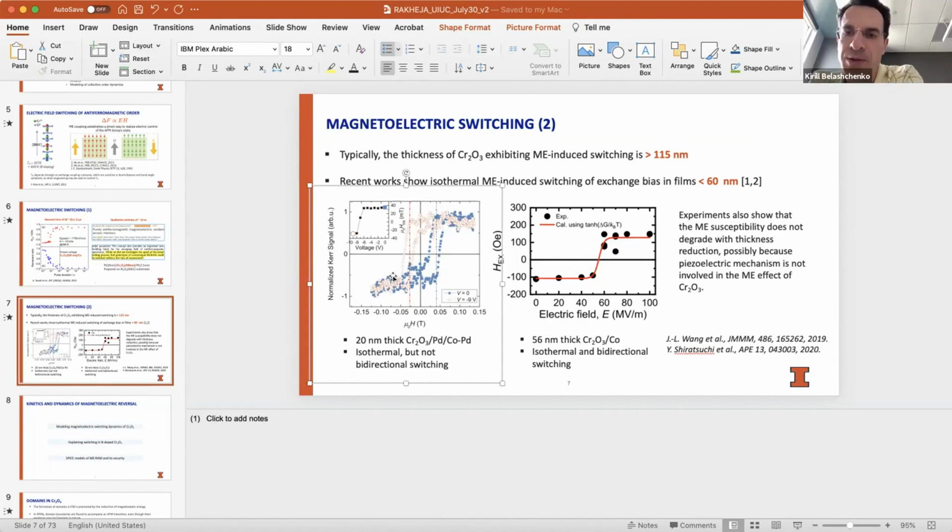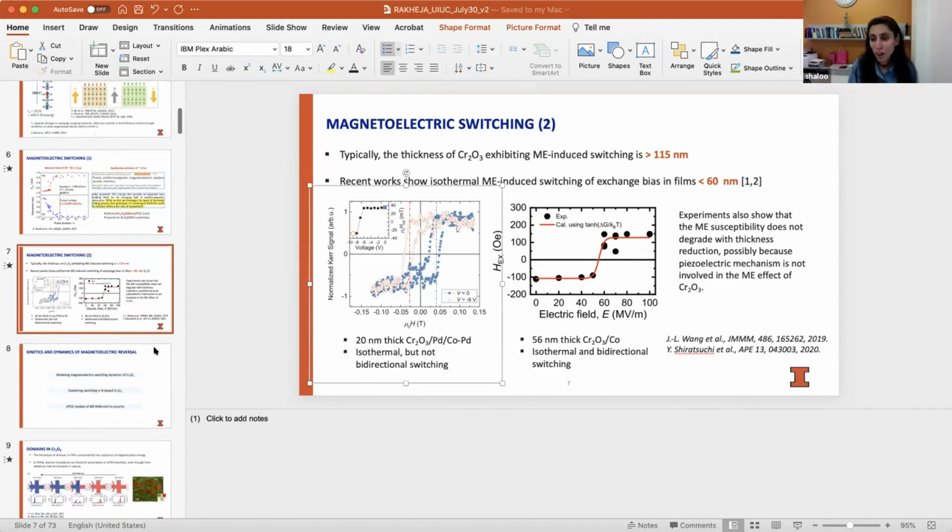And the other thing I wanted to ask: when you showed the estimate of the critical nucleus, you used the model that it's cylindrical, so that assumes that it goes through the thickness of the film. At some point, it should become three-dimensional when you increase the thickness of the film. So where is that crossover? Correct. So that's a phenomenological model. We just treat it as a fitting parameter for the model, and then we extract it by calibrating the model. Currently, we are doing it this way because of the limited amount of experimental data that is available to us.